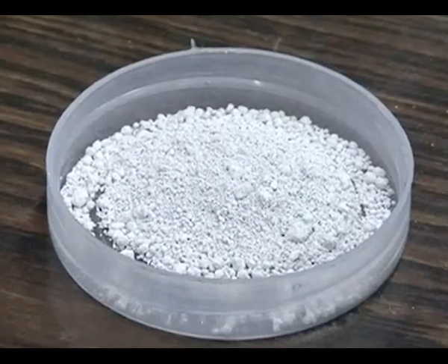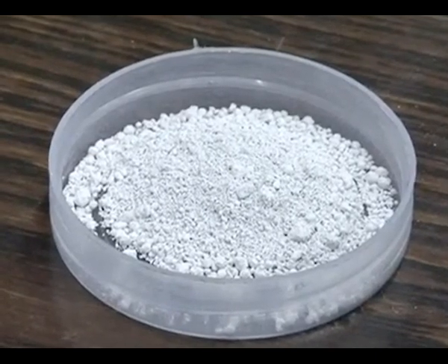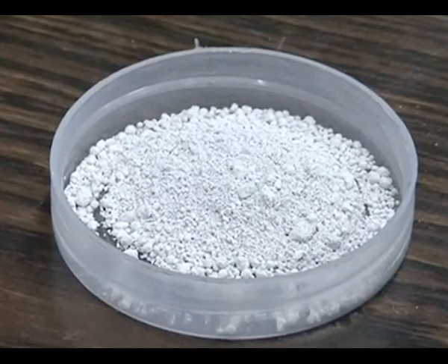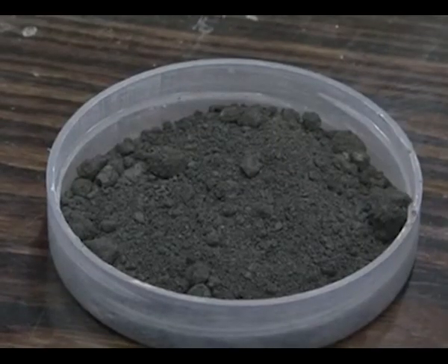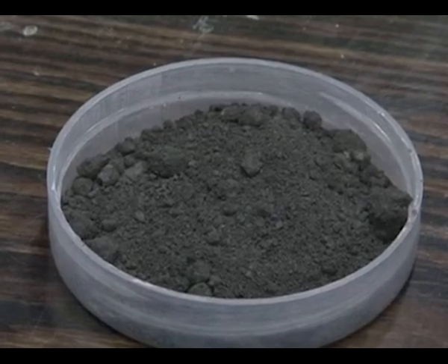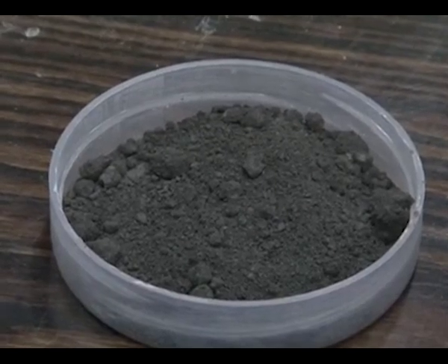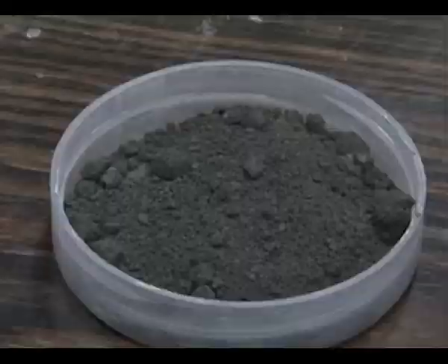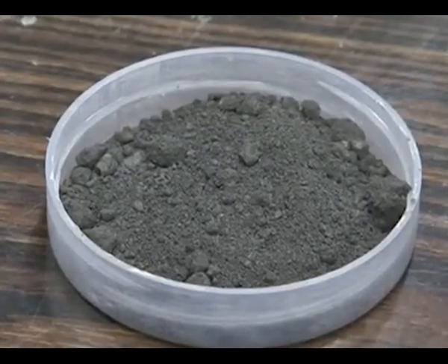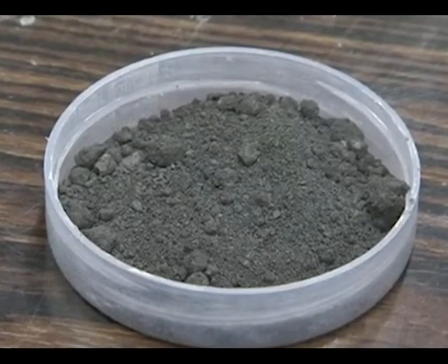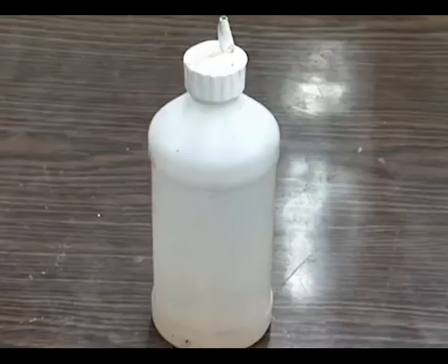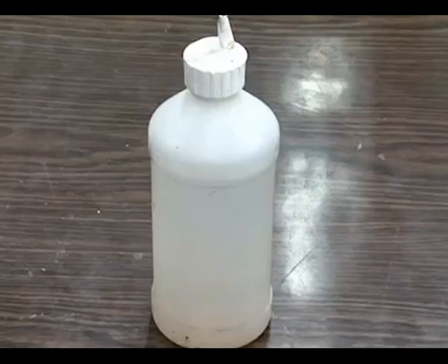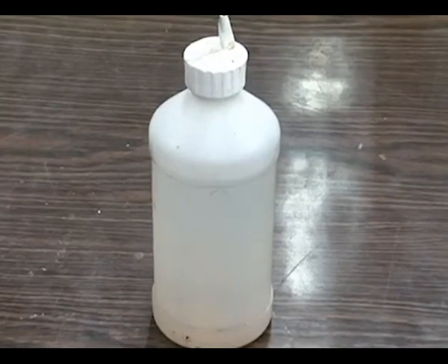Abrasive particles are required to increase material removal, in other words, to reduce finishing time. In the present case, the abrasive is aluminum oxide. Carbonyl iron particles, in other words magnetic particles, are required to make the MR fluid stiffen under the effect of a magnetic field. When the magnetic field is applied, iron particles are aligned along the line of the magnetic field and they create a dense structure. Water is required to provide a liquid medium so that magnetic particles as well as abrasive particles disperse uniformly.